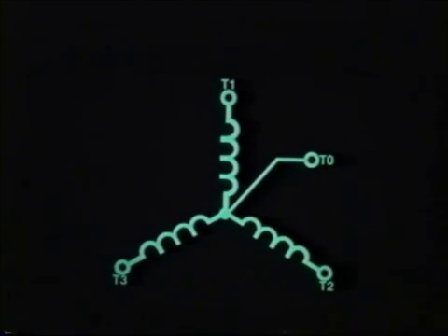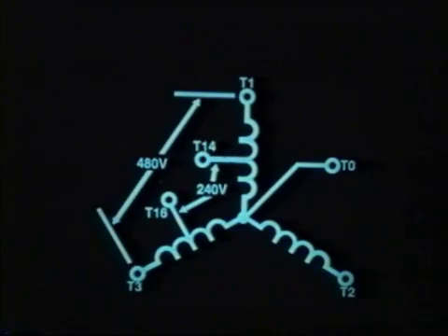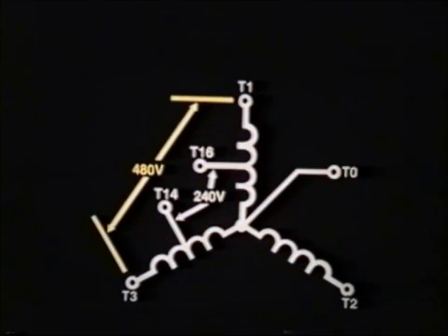Three-phase, four-lead Y-connected alternators are internally connected, with the neutral or fourth lead brought out. In some cases, a 480-volt four-wire Y-connected unit will have two phases center tapped. This provides 240-volt single phase for input power for an automatic voltage regulator.